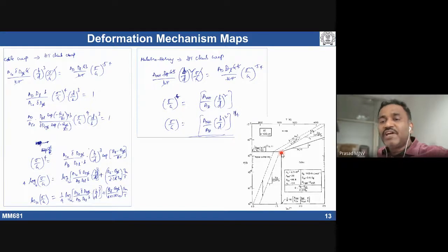That's why, between polycrystalline and single crystal, polycrystalline material has a lot of boundaries where diffusion plays a significant role. That can lead to reduced creep resistance. If there are no boundaries, as in a single crystal, we mostly see dislocation creep. The dislocation creep strain rates are high, typically. So this is how people design things. This is one way of graphical representation.